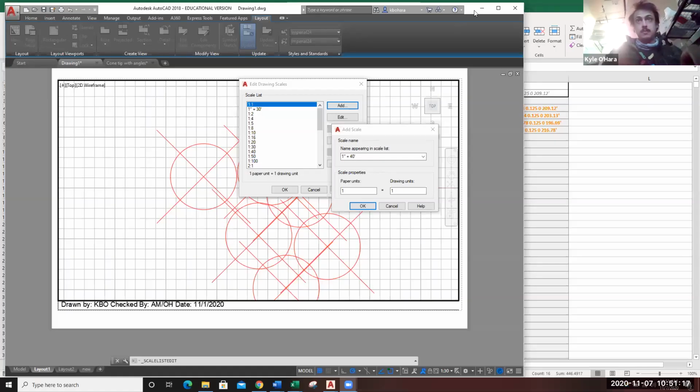Okay, so my iPad for some reason can't connect. That's fine. You saw the 1 inch is equal to 40 feet. So the upshot is, how do we convert from 40 feet to an equivalent number of inches? What's the conversion factor? Times 12. So yeah, it's going to be times 12. Does that make sense, everyone? To some degree?